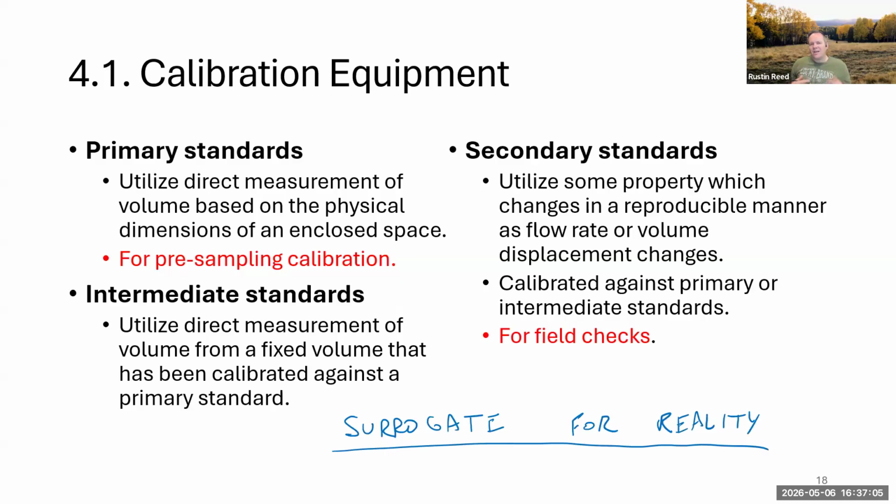We cannot know exactly what our workers' exposure was. We will not know exactly what they were exposed to. We try to get as close, as accurate as possible with our sample by sampling in the breathing zone, using the correct flow rate, using the proper setup, by calibrating, by using blanks.